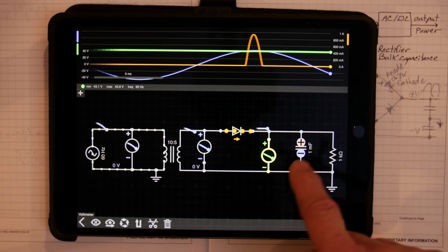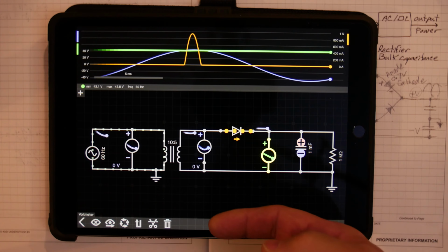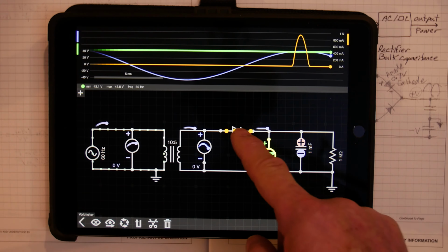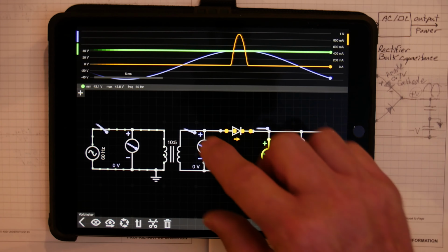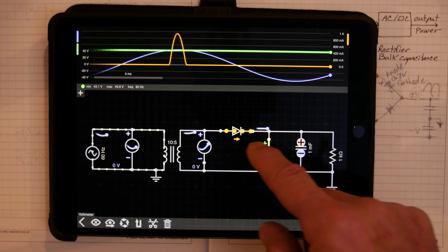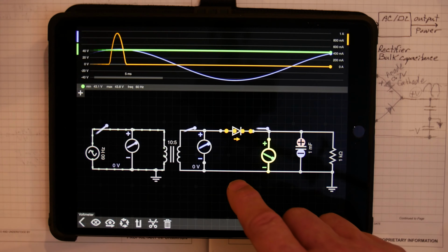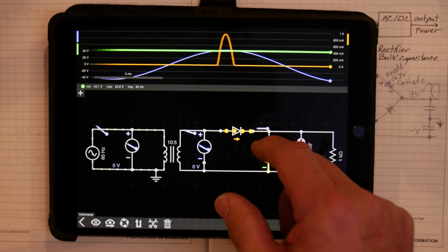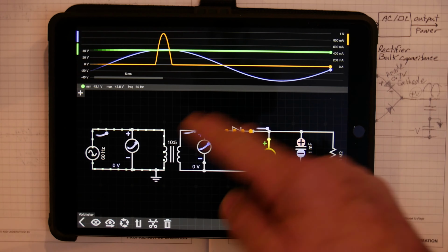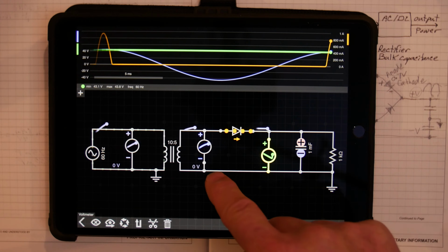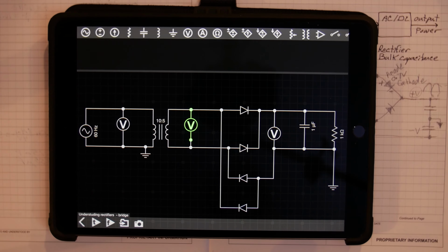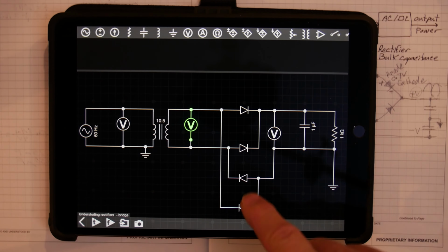So imagine if we had another diode facing that direction. Well, it really wouldn't do anything to us right now. We already are steering the current this way, but when we want to take the transformer winding and get both pulses, we're going to have to put a diode here, and that helps force the current this way during one cycle, and then we'll use 2 more diodes to switch the waveform around so that what looks like a negative pulse becomes a positive pulse on the top. Okay, so let's do that. This is what we call a full bridge rectifier. There's 4 diodes in a bridge.